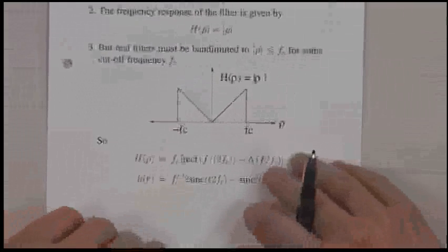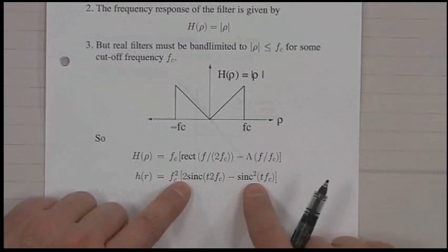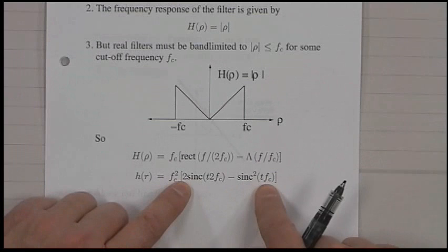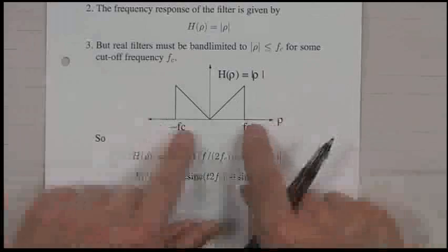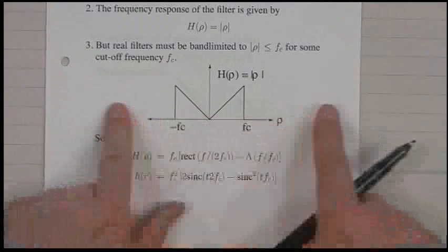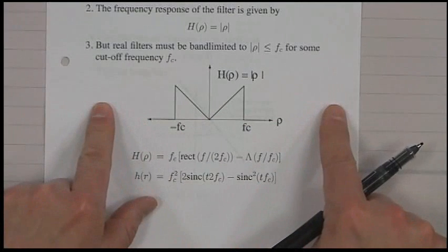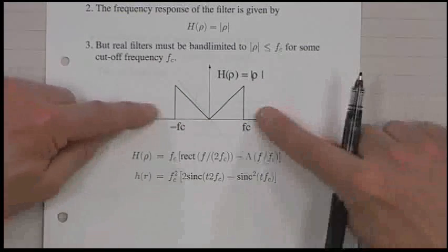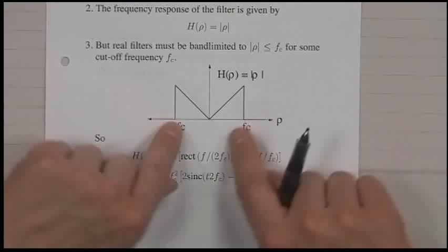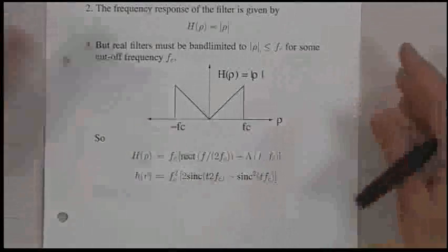So the Fourier transform of all this is going to look like a sinc minus a sinc squared, but there are some scaling constants, because when you convolved the pulse width with itself, it got twice as wide. So you have to scale it. So in time you scale it out, and that's kind of how it works.